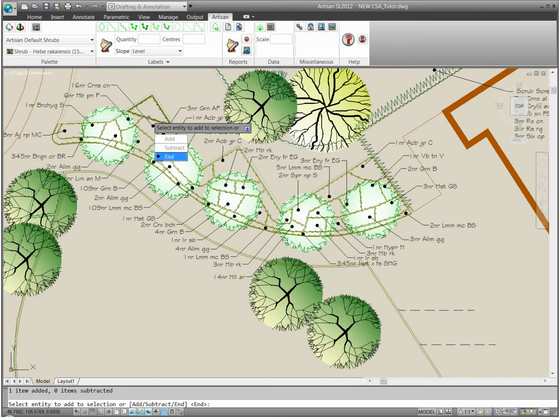Pick a point within the selected area when prompted to specify leader arrowhead location, and pick a point to insert the label at the prompt to specify landing location. The new label is inserted into the drawing using the selected label template and preferences. The leader is attached to the selected area by a rubber band, allowing the label to be moved as required.